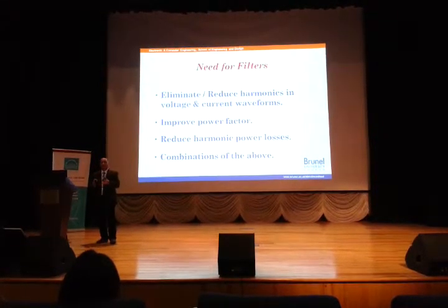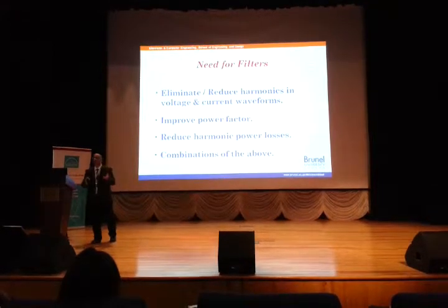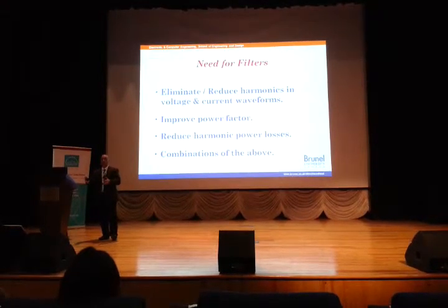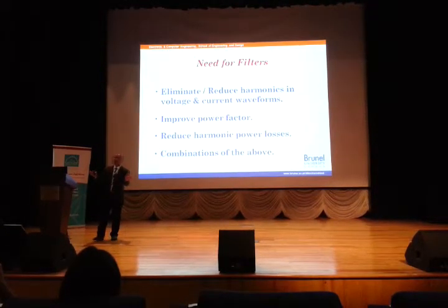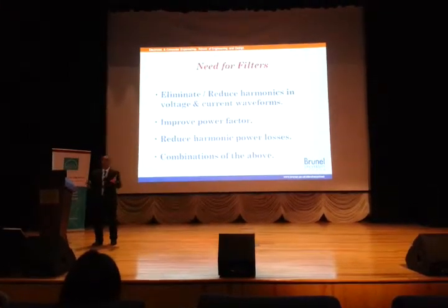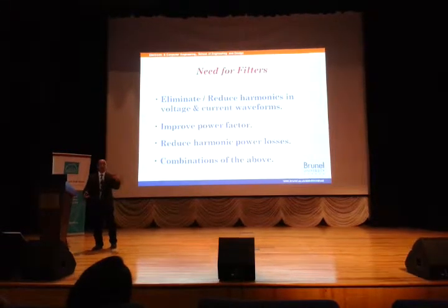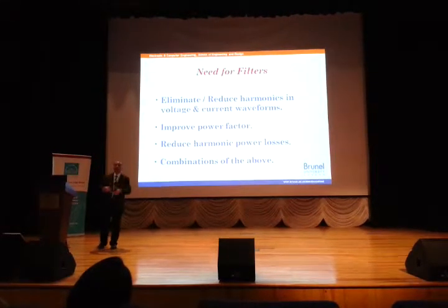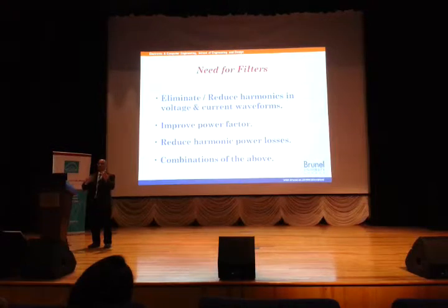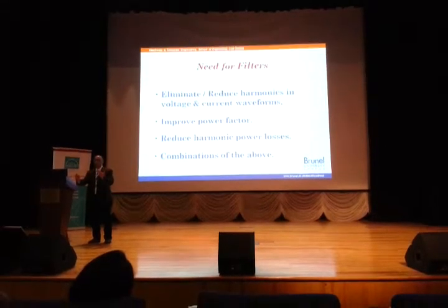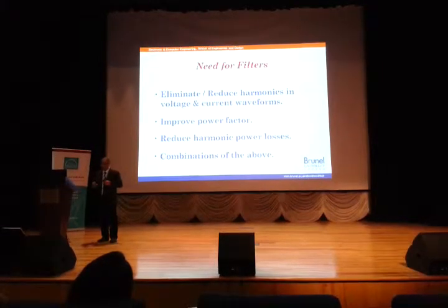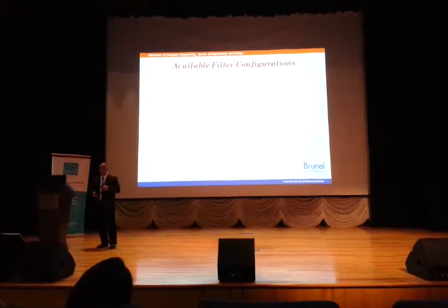A lot of people think that harmonics do not contribute to the losses. It depends. If you have, let's say, a third harmonic in the voltage, and there is no matching third harmonic in the current, there is no loss there, because simply V times I, if one of them is zero, the power will be zero. However, if I have a third harmonic voltage as well as a third harmonic current, then I have third harmonic power there, so there will be a lot of power losses. And there is not always a match between the voltage and the current. So I might have a lot of harmonics within the voltage but fewer harmonics within the current, or vice versa, or it could be a combination of all the above.